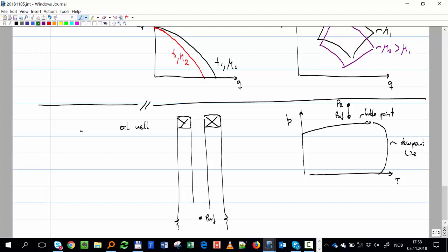Now, when we flow in the wellbore, initially we might have just single phase flow, very easy to calculate. We already know how to do it, right? Now, what happens after we pass, and here we are no longer going to be at constant temperature. If you remember the temperature distribution, it will go from reservoir temperature down all the way to some number.